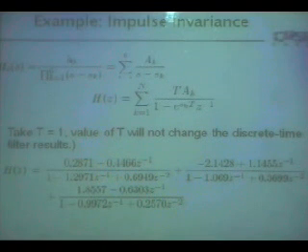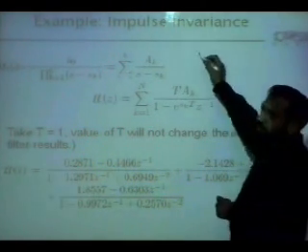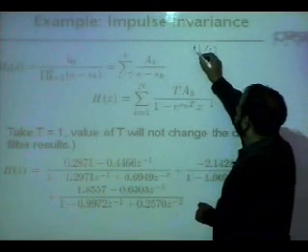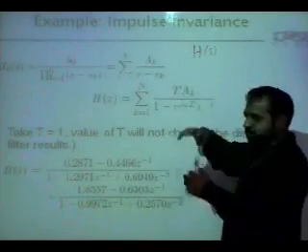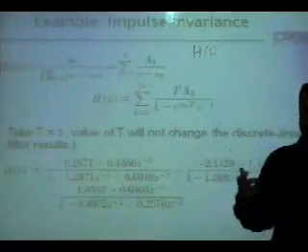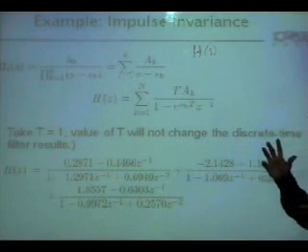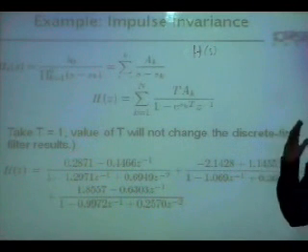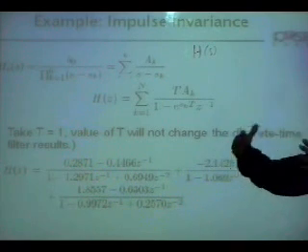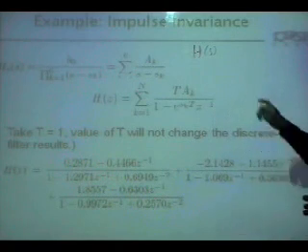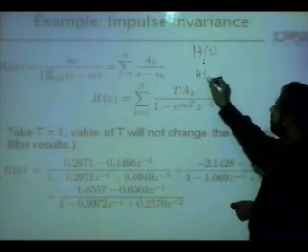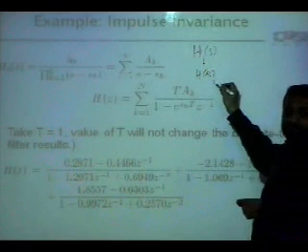Then there are established methods, and you take H of S, and it is not only true for digital filters. Any analog system with a transfer function, whether it is a control system or any system, like old radar manuals, you open that, they will give you the transfer function, that this board has this transfer function. I have actually done this, you will find H of S given. You can throw that board away and in fact convert it into H of Z, and H of Z means a difference equation.